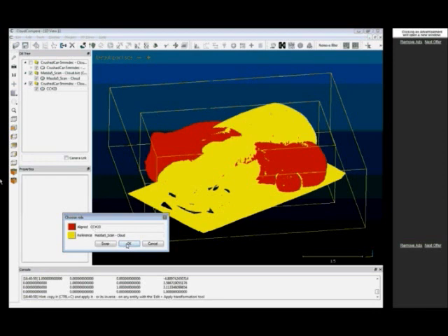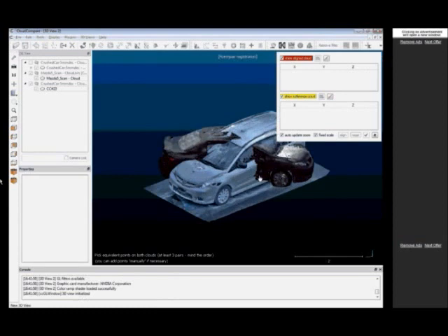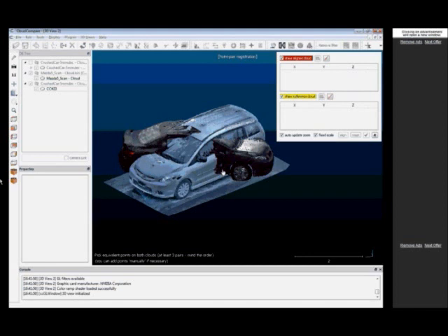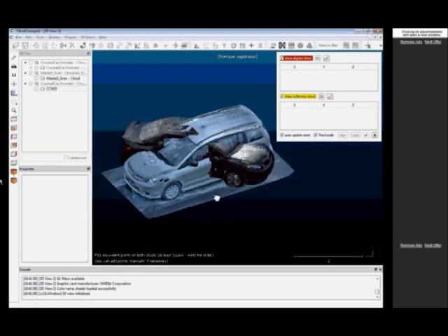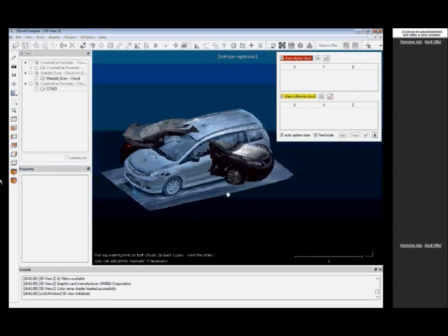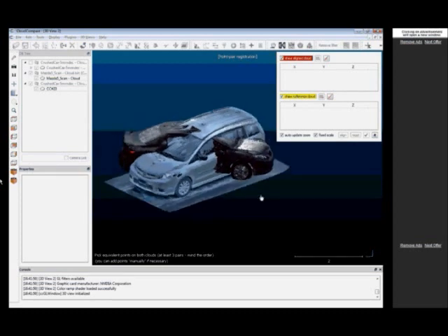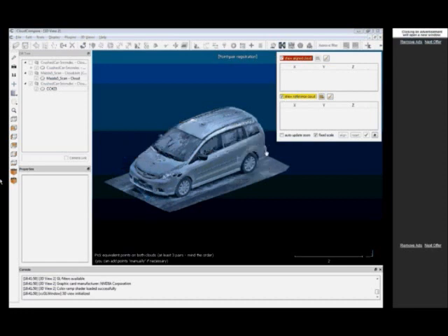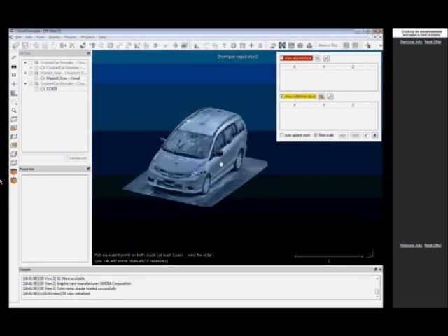So this tool, Eugene has already shipped out a great tutorial video about this, so I'll go quickly. You just have to select several points, the same points in both clouds, in the same order. You can show only one cloud at a time. It's generally easier. So I start with the blue one. Let me select quite easy points.